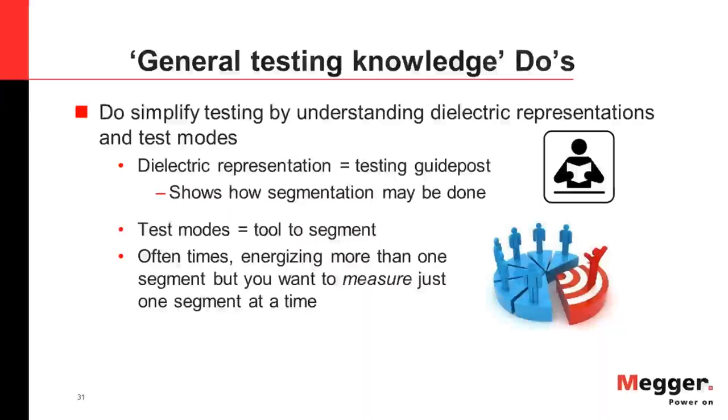For example, in this very simple image on the right of the slide, the bottom of the two images, you may be energizing that whole pie, but you're measuring just that one red slice. Which brings to mind a side note for you. When you go to check out an instrument's testing capabilities, or its capabilities to electrically charge a test specimen, keep in mind that what's actually being charged may be quite a bit more than what is required to charge the fragment that you are trying to measure.